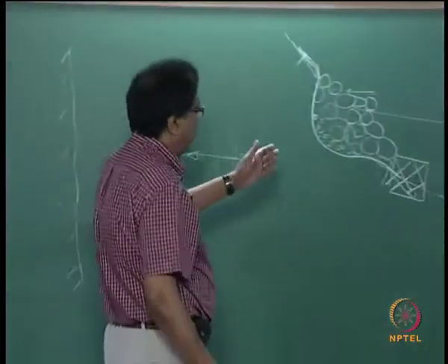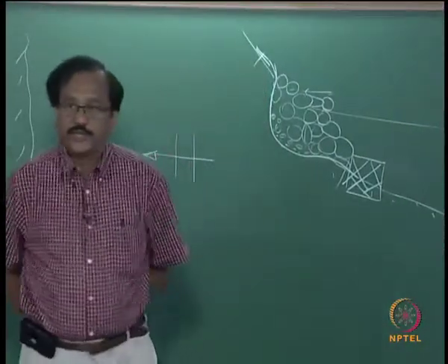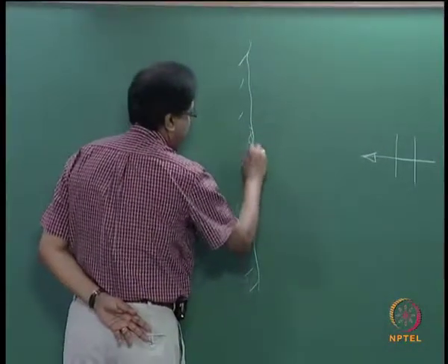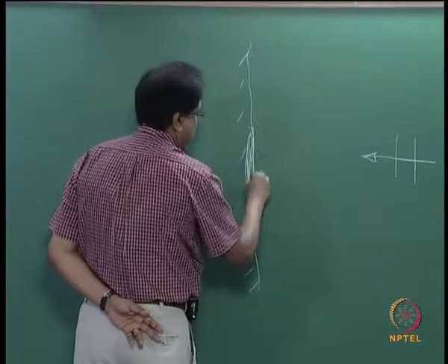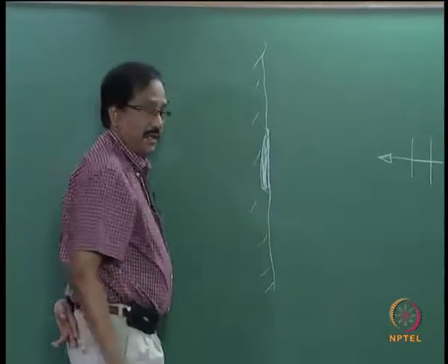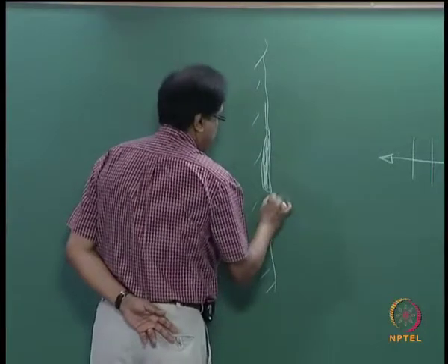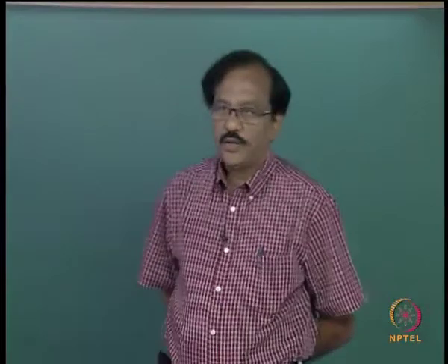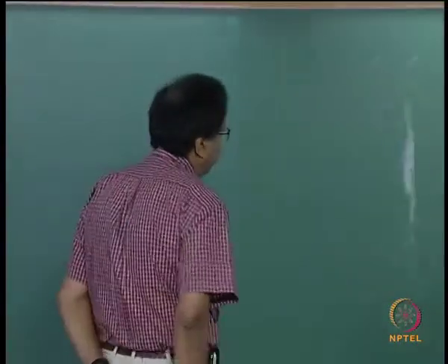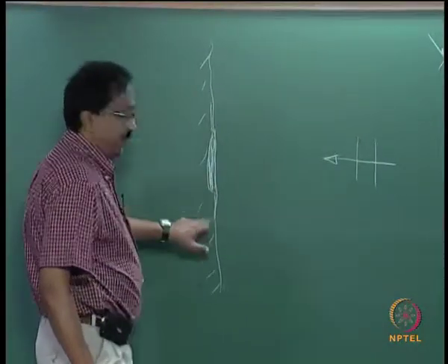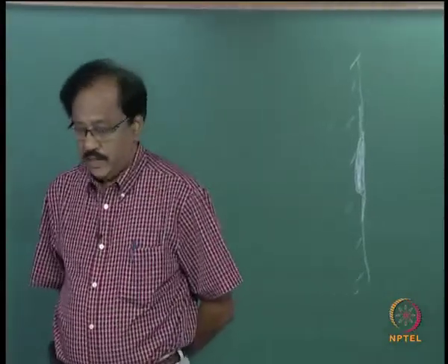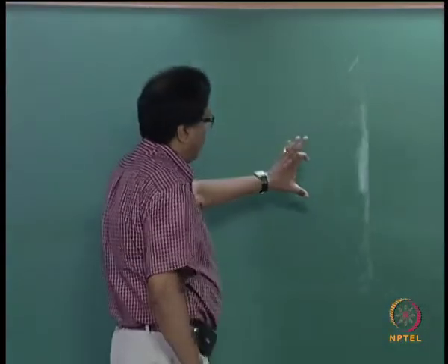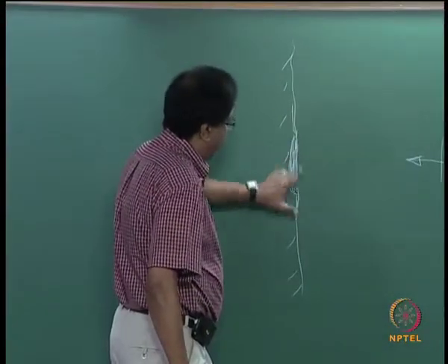So, it depends on the length of the coast which is going to be affected. If it is like this, there is no point in considering only this location. You also have to consider slightly either side of the affected area. We will also see what happens at the terminal point of the sea wall after the construction, and what happens because of the terminal effects.